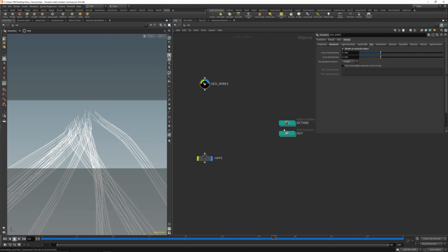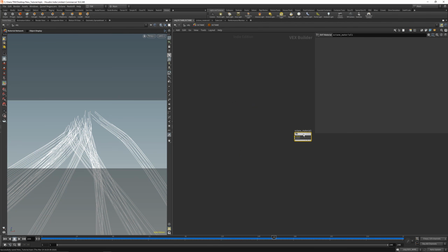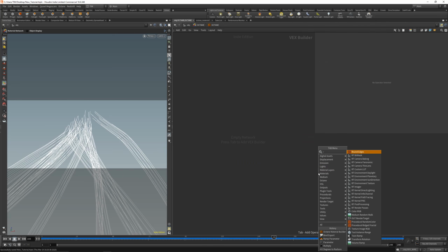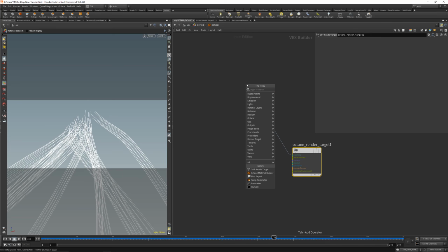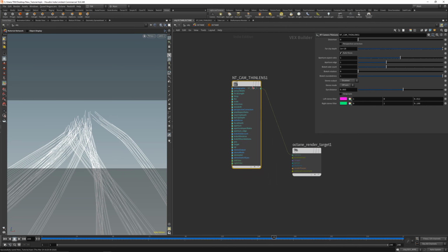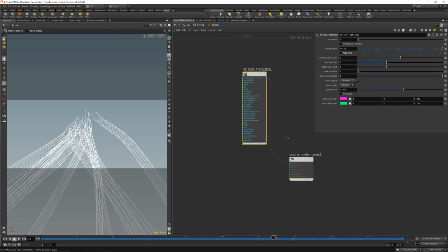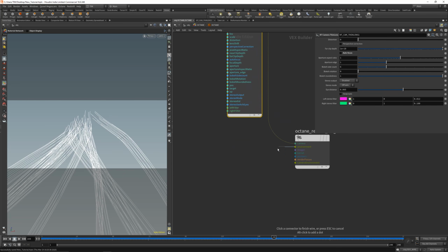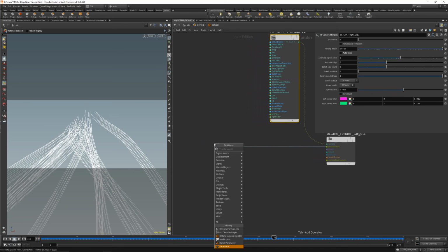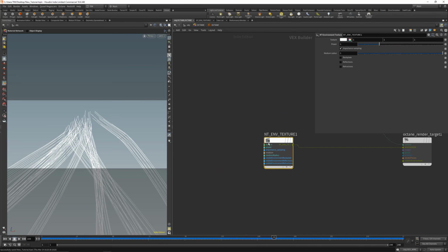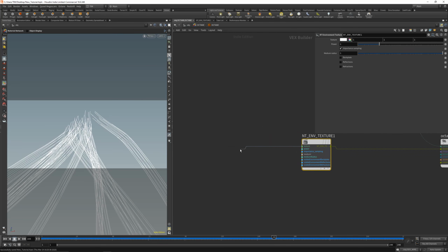Now the basic setup is done, and now we will do our render setup. Delete the Octane material and place down an out render target. We will need a thin camera lens, disable autofocus. We will need an environment and a camera environment. So the environment is for lighting and the camera environment is what the camera will see. So the environment will be an environment texture. So you can pipe an HDRI, for example, in here.